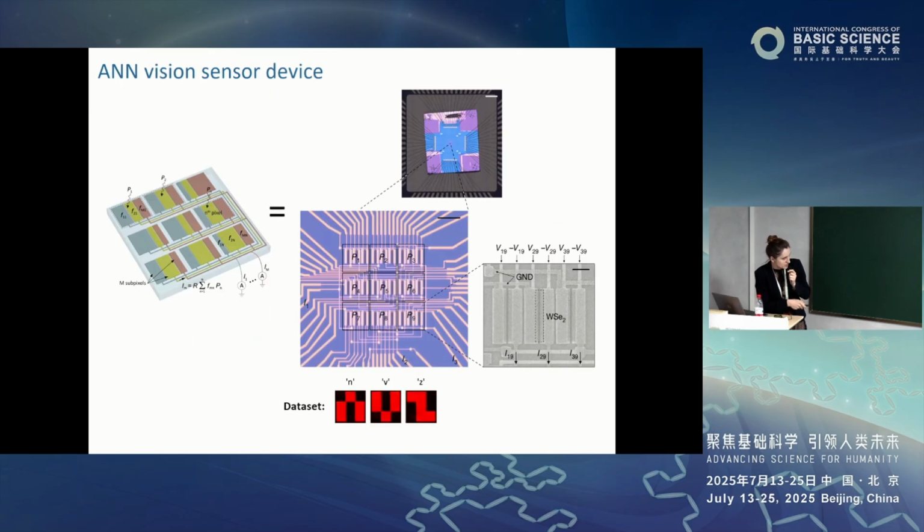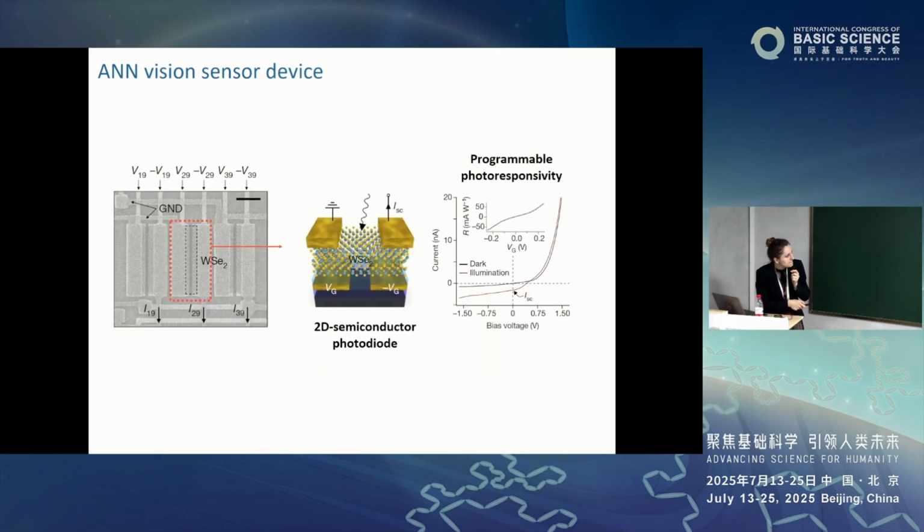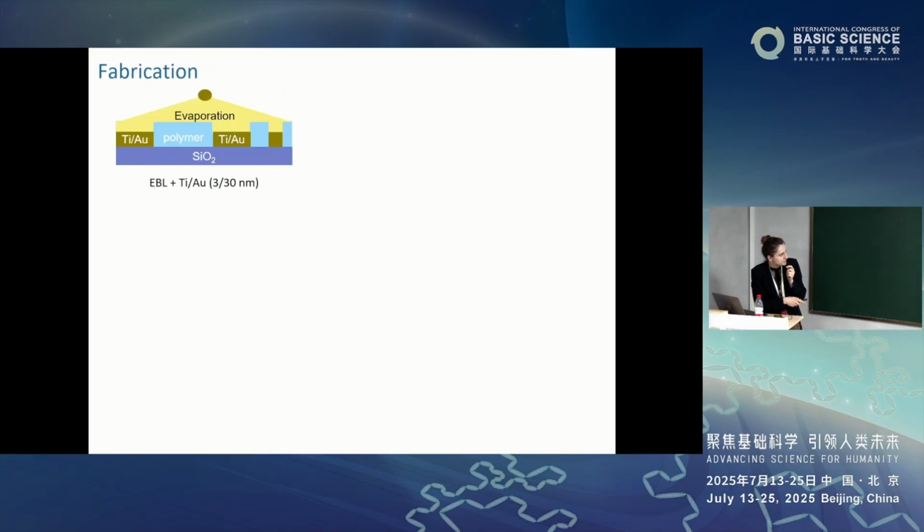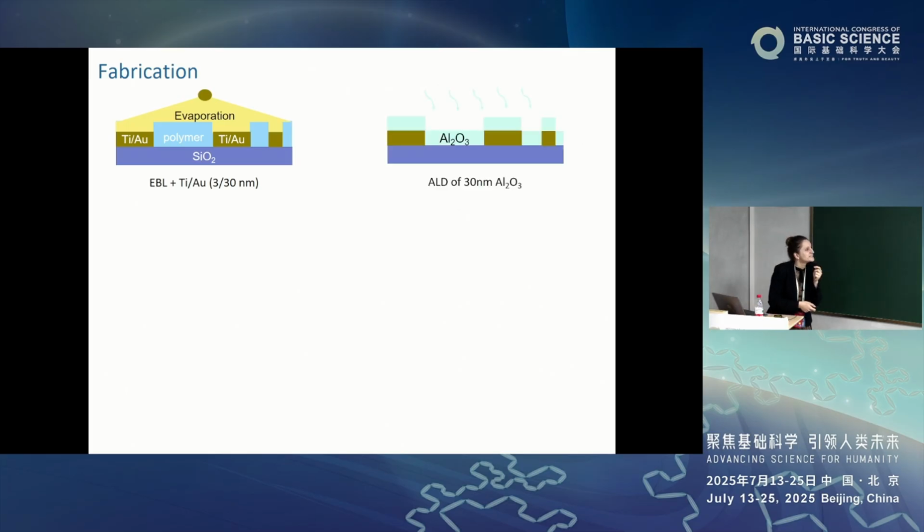Very complicated ones. So you draw it with the electron beam on the smooth substrate. And then whatever you drew gets destroyed, and then you can evaporate gold, and you will only get gold in the places where you didn't have plastic. So can anybody tell me why we need titanium? Basically the gold will not stick to the silicon oxide, so this is why we always need the titanium. It's not relevant, I'm just taking my time.